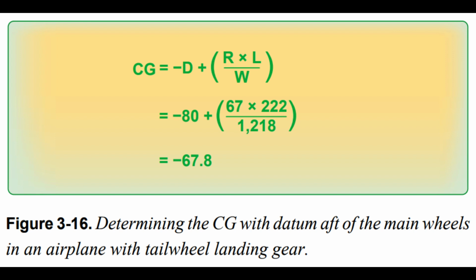On small airplanes and on all helicopters, the CG location is identified as being a specific number of inches from the datum. The CG range is identified in the same way. On larger airplanes, from private business jets to large jumbo jets, the CG and its range are typically identified in relation to the width of the wing.